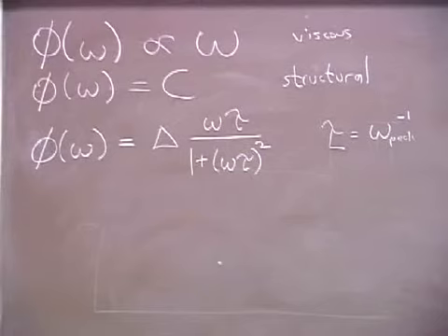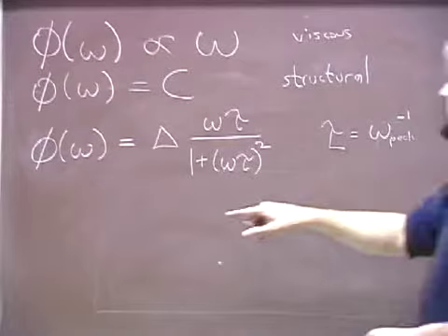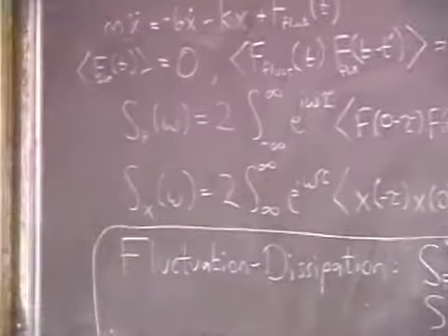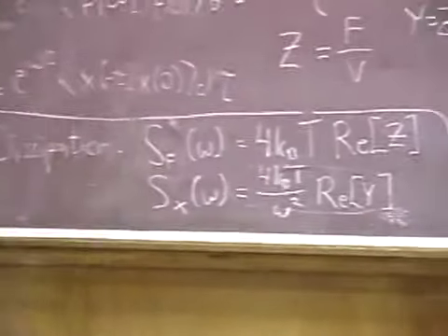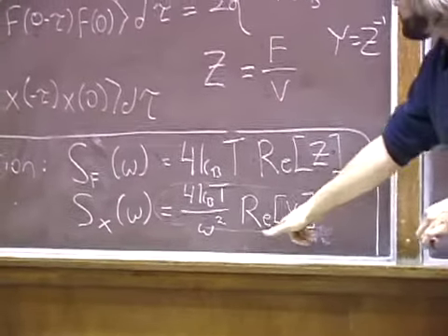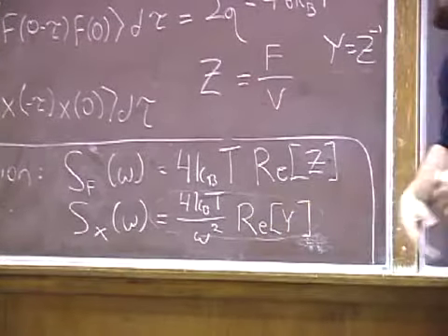Now, this is just the mathematics of dissipation. When you use the fluctuation dissipation theorem to understand what the spectrum of noise, of noise motion in a system is going to be, what you end up doing is finding the mechanical impedance of the system, the mechanical resonances of the system. It's going to have a certain response which is peaked at some frequencies and not at others.